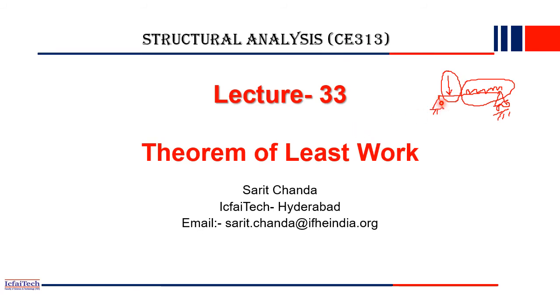So when very complex loads are acting on a structure, we discussed Castigliano's theorem method and how to solve it. Basically, Castigliano's theorem is nothing but the partial derivative of the total strain energy in a beam with respect to the load at a point, which gives us the displacement at that point. It is a very simple method: we just write the equation of the strain energy in a beam, and then if we take the derivative we get the slopes and deflections.